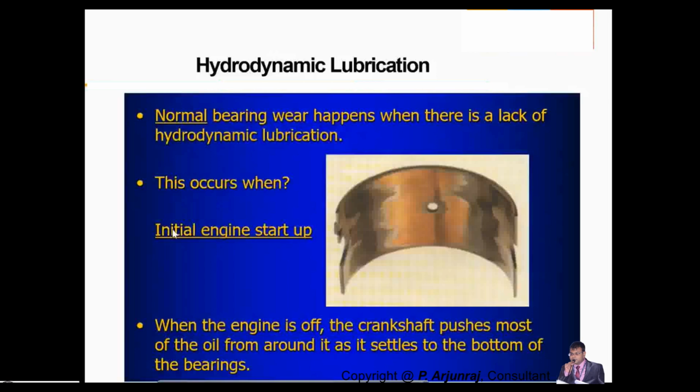Still the camshaft, the bearings, all these parts come into relative motion. You still need to have the oil even at the start of the engine. So it's not only with respect to higher RPM, because you need to have the oil at the particular place at the particular time, even during the start of the engine.